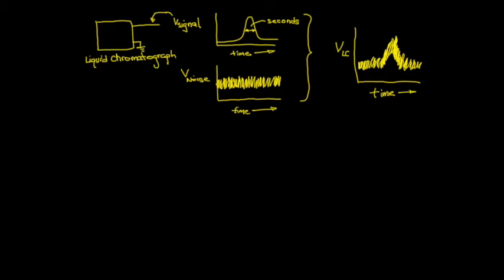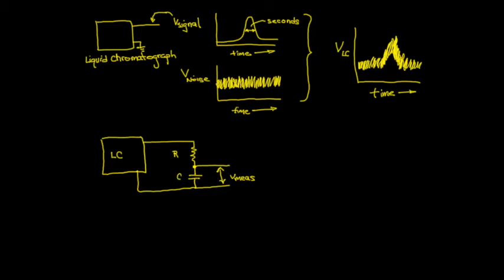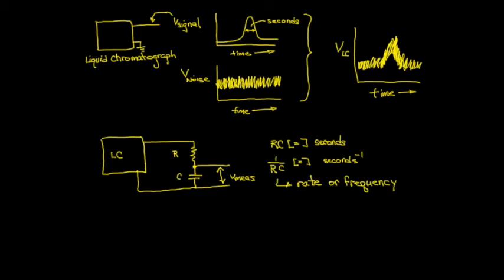Here we can use a simple RC circuit in which the voltage signal from the chromatograph replaces the voltage from the battery. We want to prevent the very rapidly changing voltage associated with noise from going on to our computer interface, but still allow the relatively slowly changing signals from our instrument to get through. Here is the key idea.